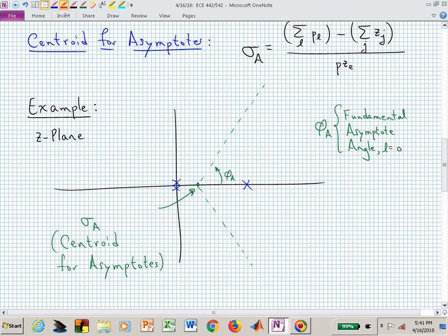So now, what's rule number 2 tell us? What's rule 1 tell us? Rule number 1 just says we start on the poles and we end on the zeros, doesn't it? We just put down the X's and the O's. We've already done that in this example. Rule 2 tells us which segments of the real line belong to the root locus.